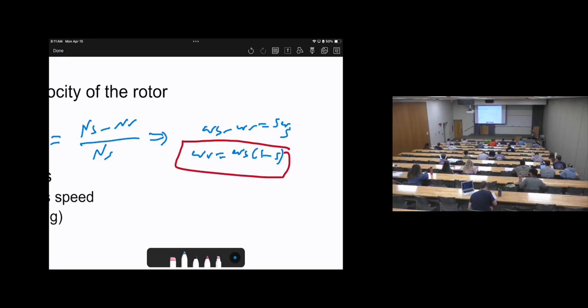That's the overall principle of how we can control the rotor. The rotor speed does not necessarily equal omega s. It can be omega s or less than that, so it can change, following 1 minus s. The highest velocity it can reach is when omega r equals omega s, which is when it reaches the synchronous speed, while I can reduce it lower than that. For example, if the motor is designed to work at 1800 RPM, the maximum speed it can reach is 1800, and I can control it lower than that.